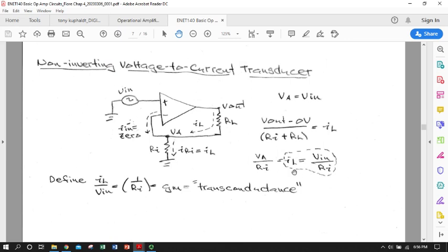Now, of course, if I knew what my load resistor was, then I could multiply by that and know what this circuit point was. But the idea of this whole thing was to get a controlled current. So I'm going to want to express the gain effectively in terms of a current. Instead of a gain, we get a current to voltage ratio. This is called a transconductance.